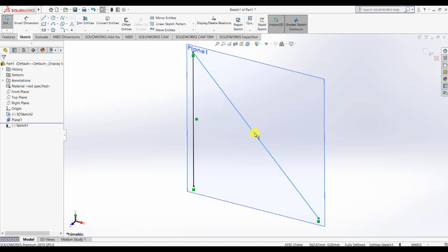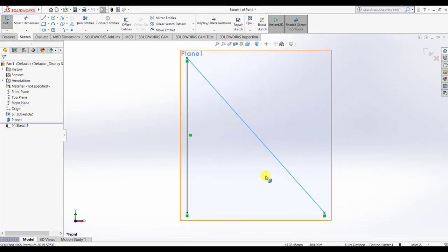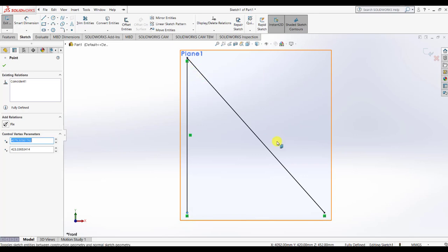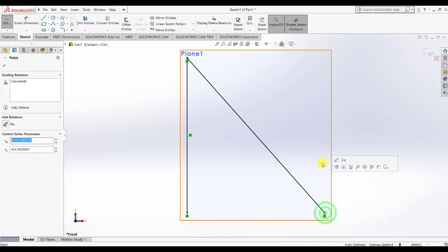The location of the point must not be changed, because the location decides the geometry, and the shape decides what amount of forces the wishbone will be able to take. Suppose the wishbone is able to take all those loads if it is simply connected, I recommend going with the simple design. If it is not able to take that and you are further optimizing your design depending upon the shape of the arm, then obviously you can have a variety of shapes. The only recommended thing is you don't move the point. This is how you take all other points and make your part.